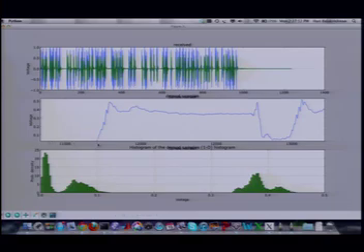It goes from a 0 to a 1 sharply on the input, but it takes a while to go from a 0 to 1. And then I want to go from a 1 to a 0, and you can see that as it comes down to 0, it takes a while to settle down. Do you all understand why that happens? I don't mean the physics of why it happens, but how that idea relates to the unit step response and the unit sample response. This is nothing more than the unit step response of this channel, right?